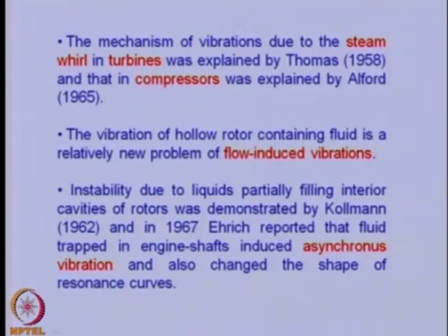The vibration of a hollow rotor containing fluid is a relatively new phenomenon of flow induced vibration. Instability due to liquids partially filling the interior cavity of rotors was demonstrated by Coleman in 1962, and in 1967 Ehrich reported that fluid trapped in an engine shaft introduced a synchronous vibration and also changed the shape of resonance curves.